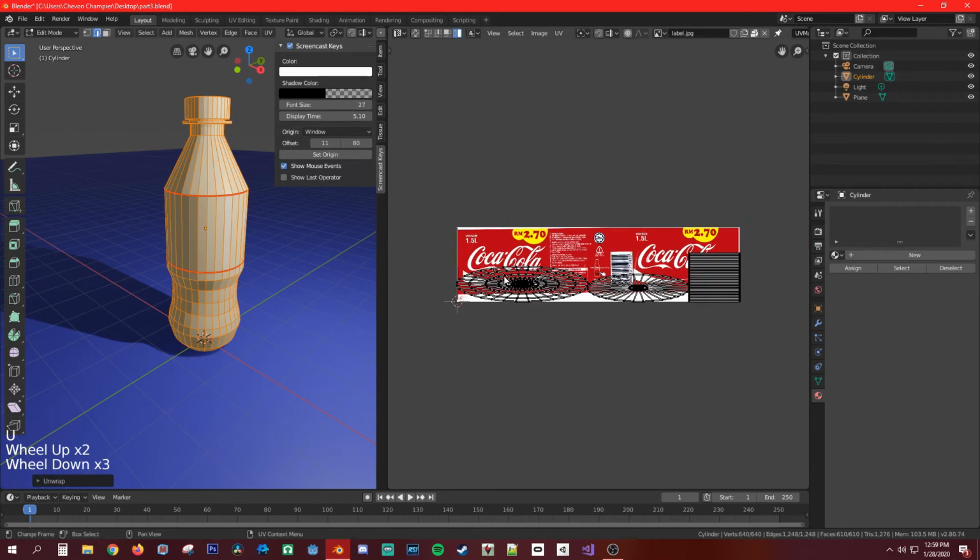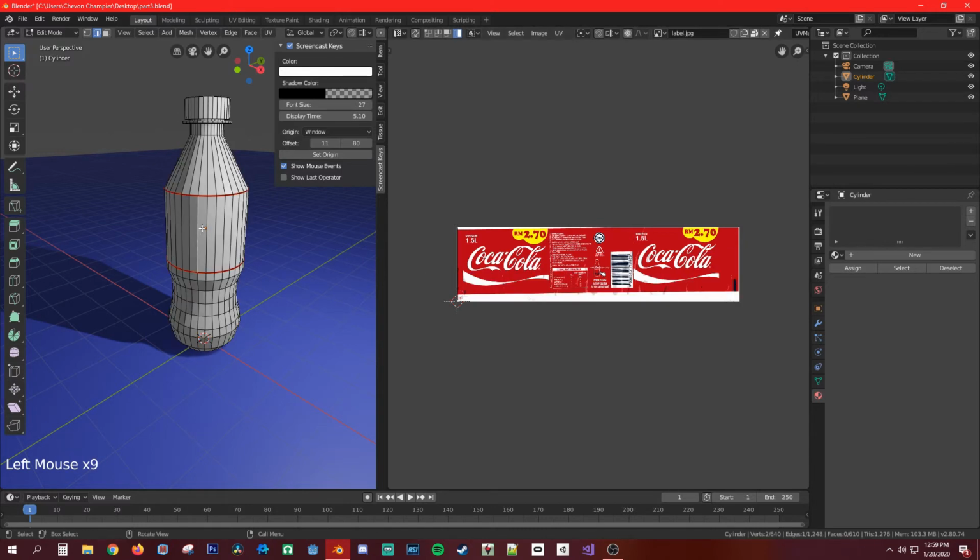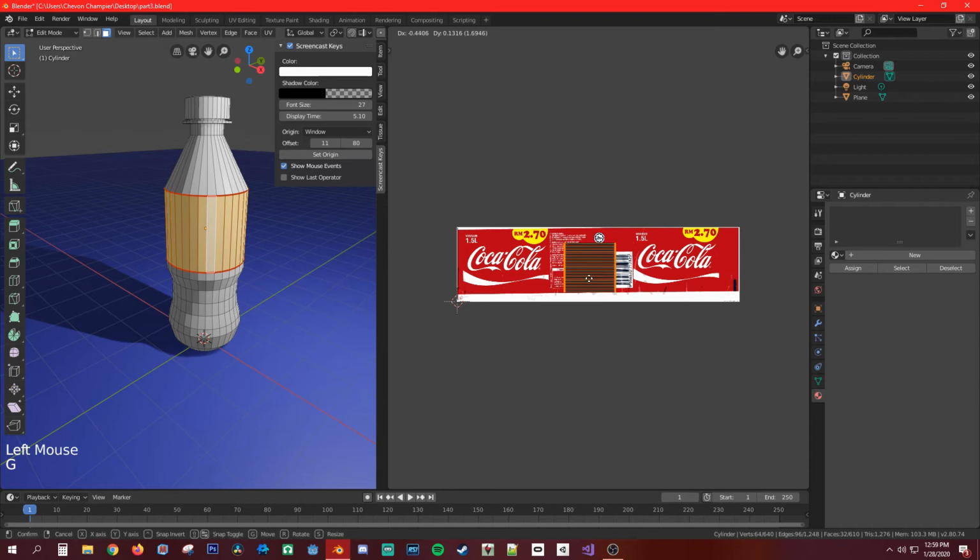and we don't really need these parts, so we're gonna get rid of them. Not really get rid of them, but I'm gonna use them differently. So go to face select all of these. Then over here you could hit island select mode. I'm already there, so click that and grab it, move it to the middle, and rotate it.